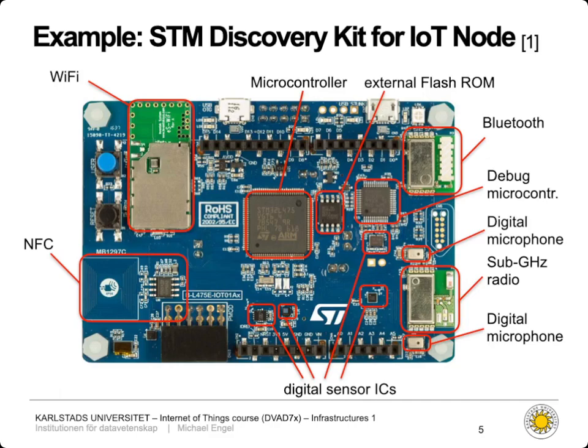And then you have all the radios. So you already see these radios are somehow on green pieces of PCB. So these are separate PCBs soldered on top of the blue basic PCB. So usually, due to certification requirements, including an antenna and so on, all these radio modules come on separate PCBs and separate modules, which are independently certified. So you can just use them as a whole package and can solder them on top of your application IoT node PCB.